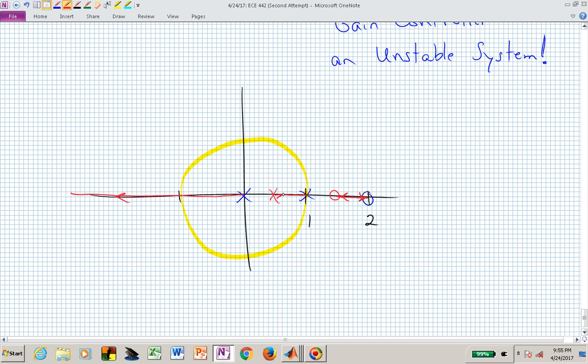So these two poles will approach each other. They will hit and break away, and those two will re-enter between the finite zeros, and we have a third branch of our root locus starting at the origin and going off to minus infinity.